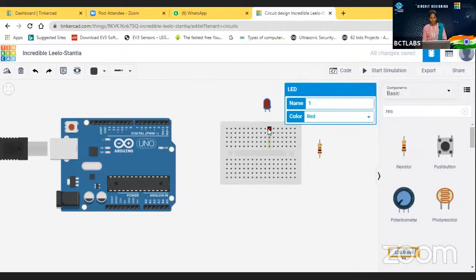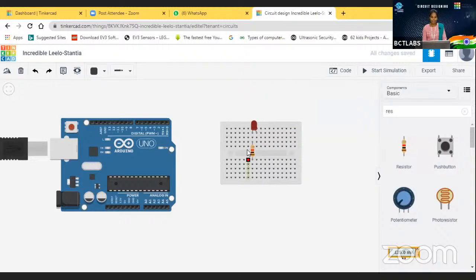In a breadboard, it has parallel and serial connections. Here in this mini breadboard, we can find a parallel connection alone. So I'm going to fix it here. Once you connect the supply, it will flow in a vertical manner, so all the strips in the same line will get power. So I'm using this one. Then I'm going to connect a resistor to the negative end of the LED, that is the cathode.